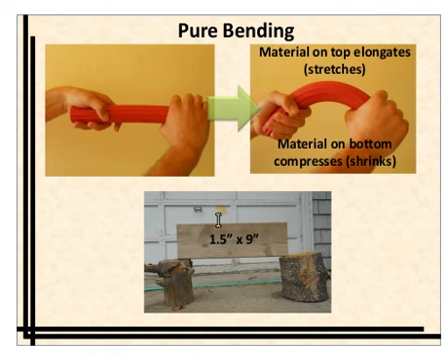A lot of the concepts I'm going to discuss later can be thought of conceptually as a form of bending, or pure bending is what I'm calling it here. Pure bending is what occurs when you apply moments to a beam-like structure. So here's an example. I have this piece of foam, and I apply moments to each end of this beam, and it assumes this deflected shape. Now when I say moments, that's the term that's typically used in engineering. The word torque is accurate as well.